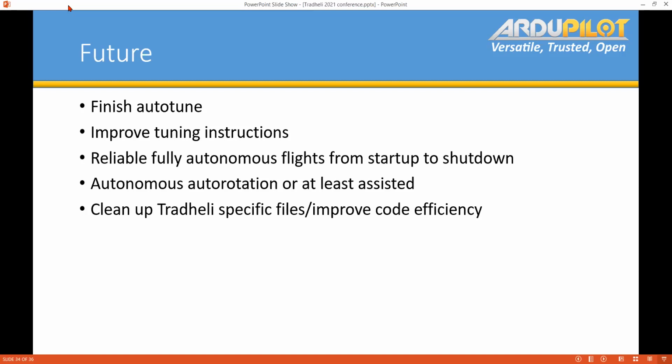And if it does, if it's a rotor regressive mode or feedback stability mode, that would not be good because we don't have the ability to notch as many modes as we want. We still have that other static notch, which could be used, but definitely have to keep it from exciting the mount.